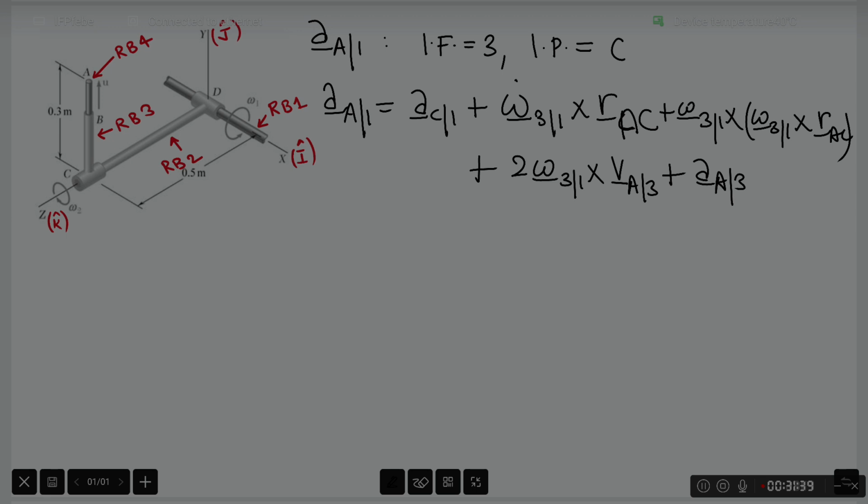Like last time, what I did for the velocity transfer relationship, I will start sweeping from right to left and mark the known quantities as K and the unknown quantities as U. I start with AA3. Is AA3 known? Indeed, AA3 is known from the problem statement itself.